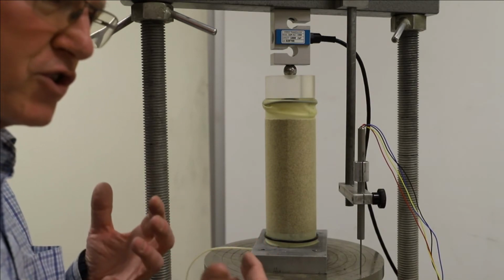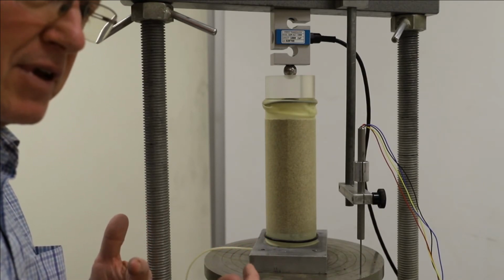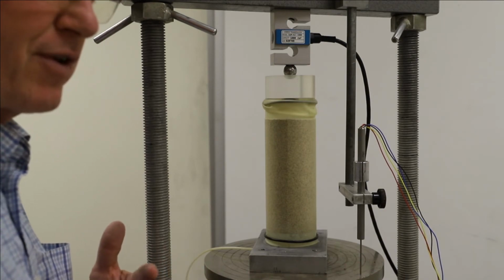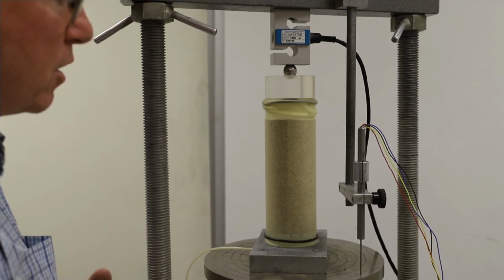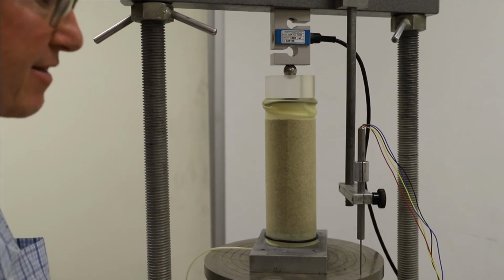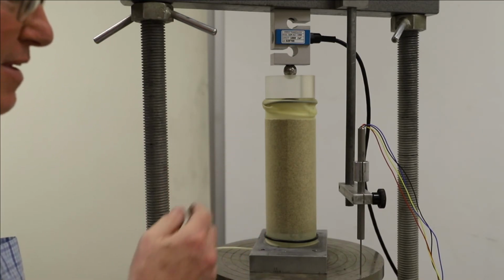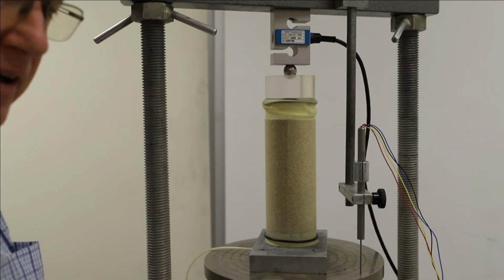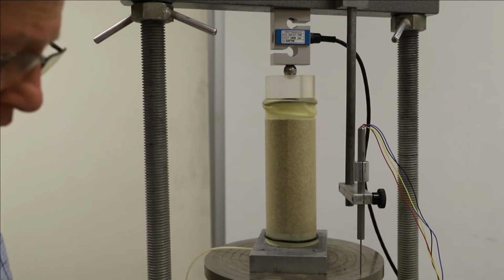So when it goes to shear, instead of contracting and becoming denser and therefore moving the failure to some other plane in the specimen, failure should result in dilation, right, in a dense specimen. So we should see a pretty different sort of mode of deformation in the sample, and also you'll see that hopefully in the data file that you're going to process from the testing.